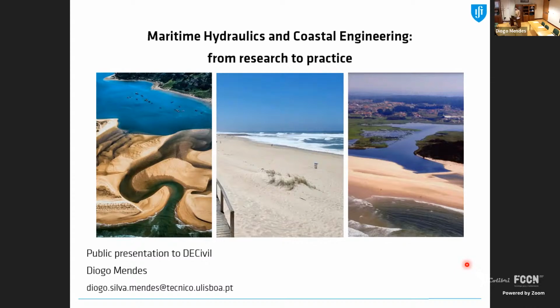But thanks for your question, because, for example, American colleagues for a very long time used to place beach nourishments at the surf zone of the beach, based on sediments that were dredged from offshore pits. And usually you get finer sediments than the ones that are native in the sand. So there is some knowledge about how finer and coarser sediments behave in terms of beach nourishment solutions. But when we are talking about morphodynamic models, it's like in rivers. You have some formulations, but they were obtained for certain characteristics, and in real processes it's very difficult to get those characteristics. For example, just to finish my response,